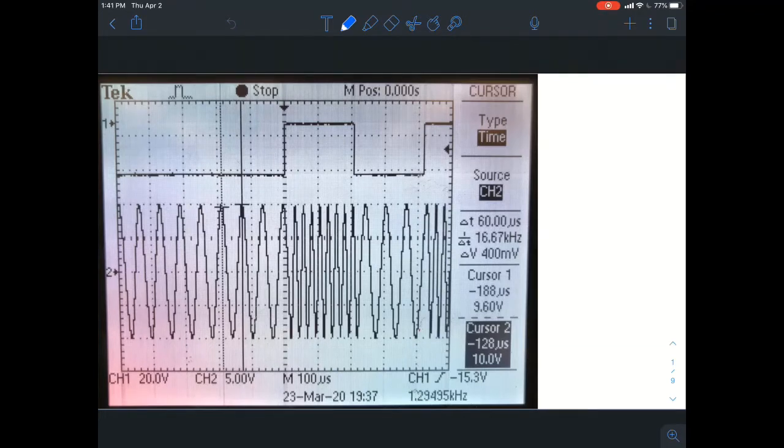So the actual security exercise opens with looking at a frequency shift keyed signal, which we have here. We can see that we have some zeros and some ones. In the zeros, we have our space frequency, which is our lower frequency, and then we have our mark frequency, which is our higher frequency.